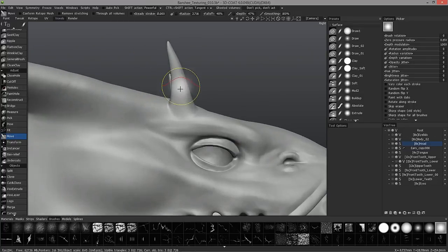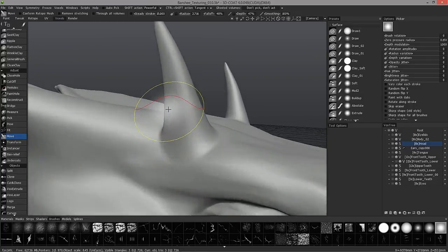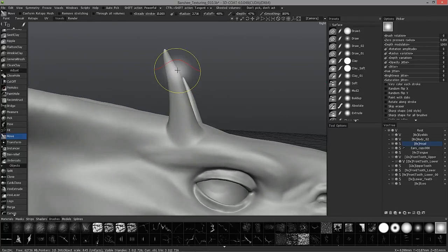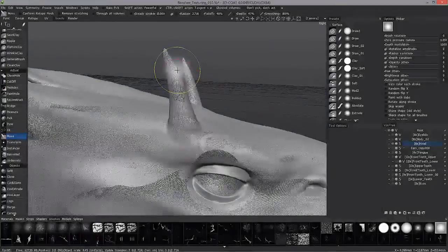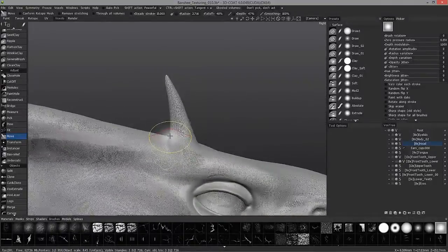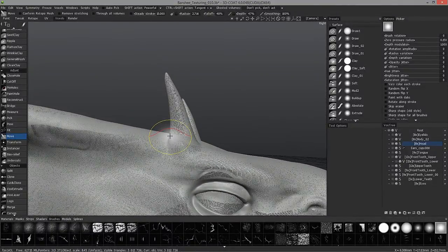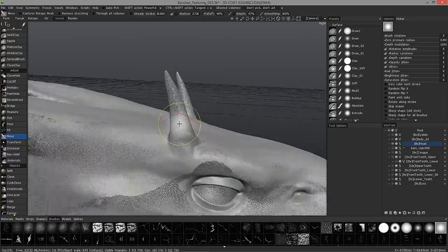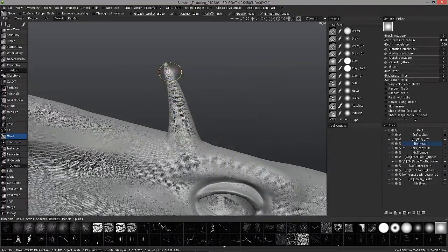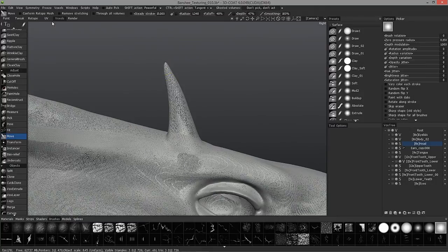But you'll notice when I hit the wireframe hotkey, which is W, you'll notice I got a lot of stretching here. Okay, so there are a couple ways that I could attack this. One is when I'm going to do this type of operation where I know ahead of time that I'm going to stretch, I can choose to select remove stretching.